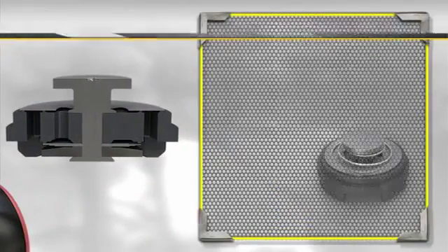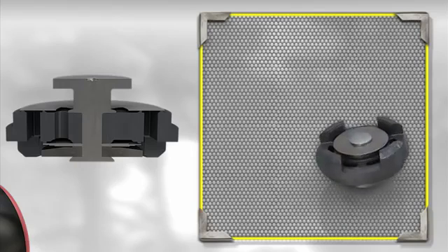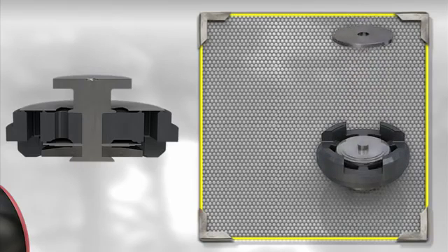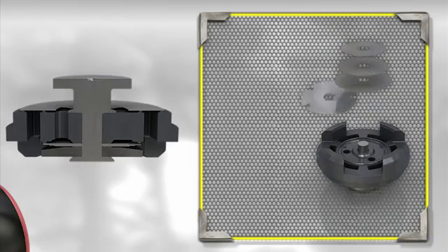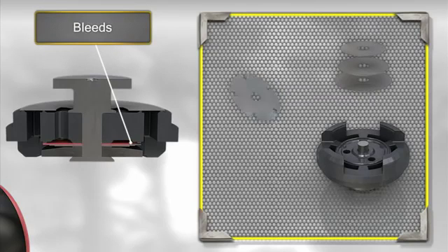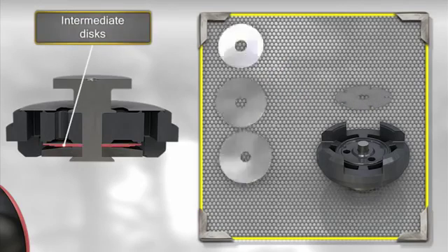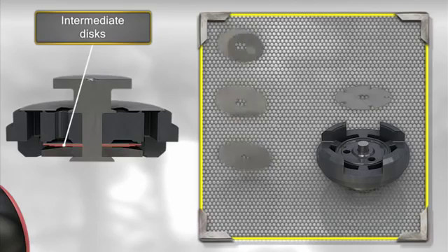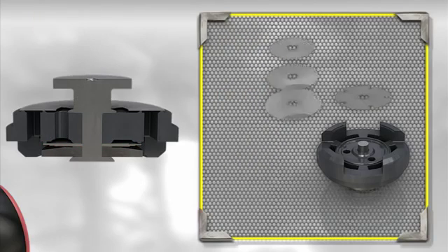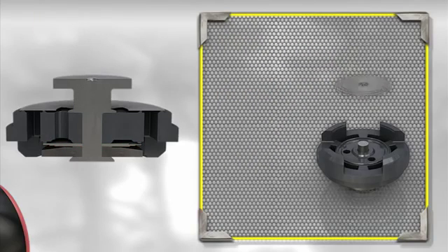In twin-tube shock absorbers, we also find a compression valve at the base of the working chamber tube. The configuration of this valve is similar to the piston valve, but inverted. It is also smaller in size because its design takes into account the damping force provided by the coil springs during compression and other elastic elements of the suspension system.